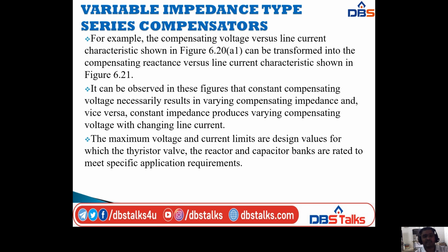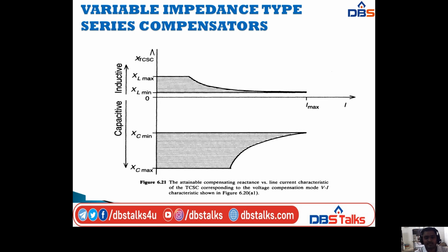Okay, next. Here I am taking, for example, the compensating voltage versus line current characteristic that is shown in the A1 diagram in Figure 6.20, which can be transformed into the compensating reactance versus line current characteristic that is shown in the 6.21 diagram, that is this one. So this diagram is for the attainable compensating reactance versus line current characteristic of the TCSC corresponding to the voltage compensation mode, that is the VI characteristics of the 6.20 A1 diagram.